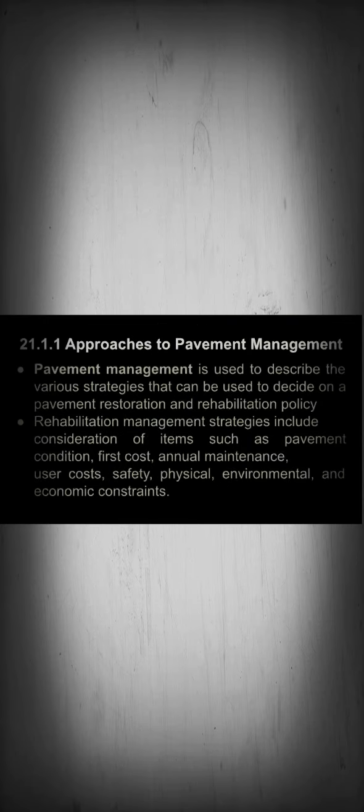Approaches to pavement management. Pavement management is used to describe the various strategies that can be used to decide on a pavement restoration and rehabilitation policy. Rehabilitation management strategies include consideration of items such as pavement condition, first cost, annual maintenance, user cost, safety, physical, environmental, and economic constraints.